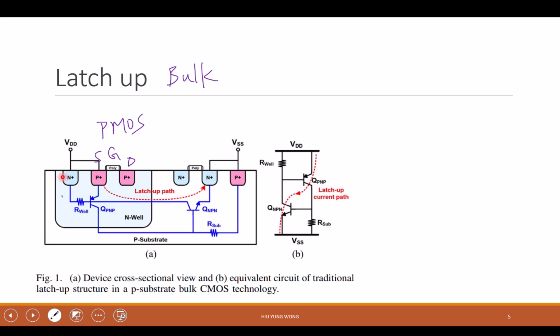So it is inside N well, and N well because a PNP that form a transistor, right? But this N well I need to bias it, right? So this is the body of the PMOS. In the same wafer, this is a continuous silicon. We also have the NMOS, right?